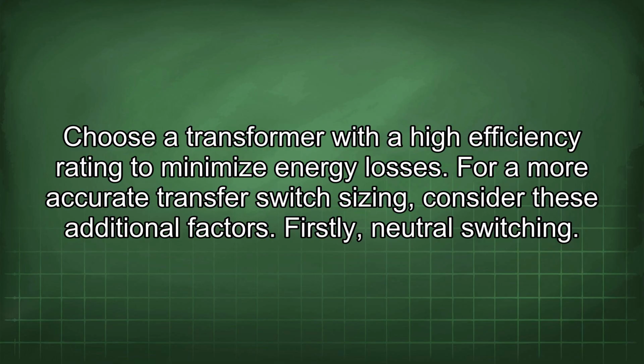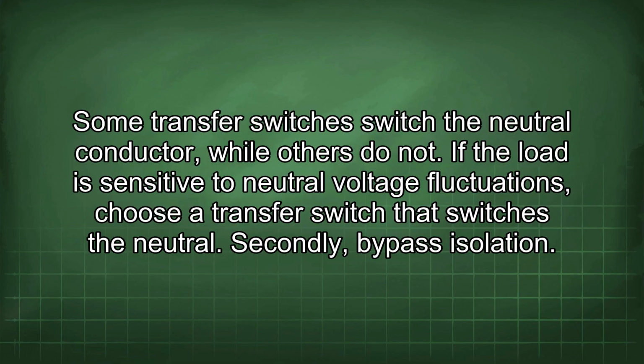For a more accurate transfer switch sizing, consider these additional factors. Firstly, neutral switching. Some transfer switches switch the neutral conductor, while others do not. If the load is sensitive to neutral voltage fluctuations, choose a transfer switch that switches the neutral.